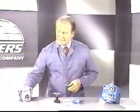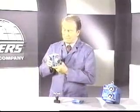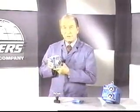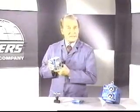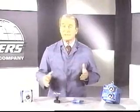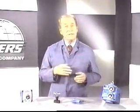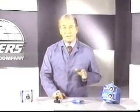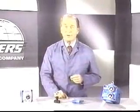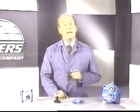Now, let's take a look at a flow control that has an additional benefit. We all know that the temperature of oil affects its viscosity. We can get more hot, thin oil through an orifice at any given pressure than we can cold, thick oil. Any change in the temperature of the oil changes its viscosity, which in turn changes the rate of flow through our flow control and the speed of the cylinder piston.